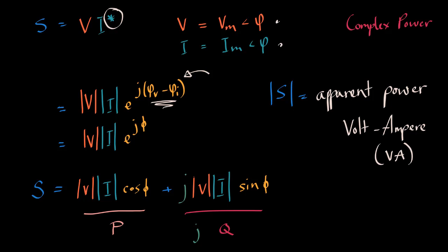Note that the apparent power can be equal to the real or active power, but only in the complete absence of reactive elements in the network. We now have the three ingredients for our triangle of power: active, reactive, and apparent power. They can be visualized in the following way.